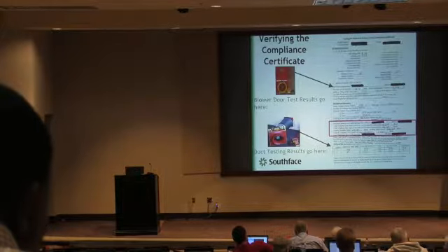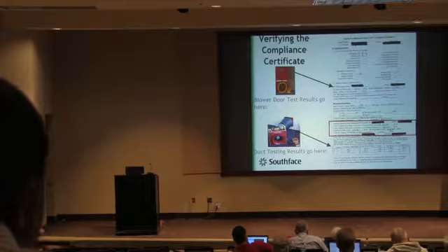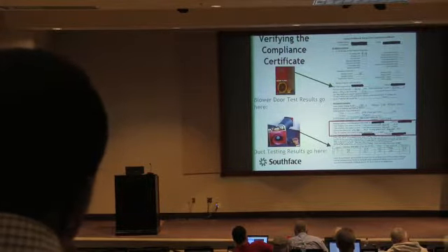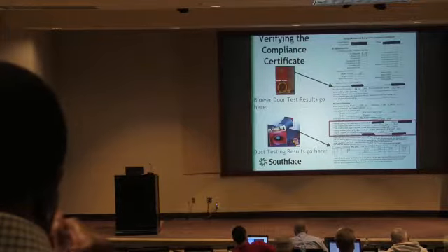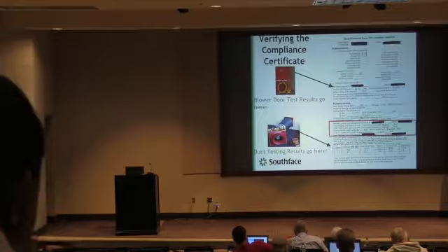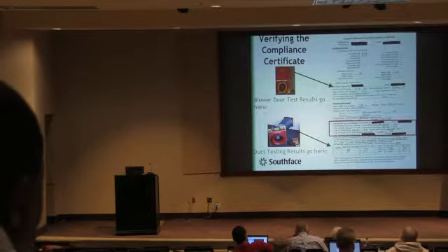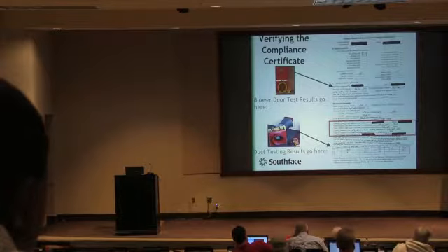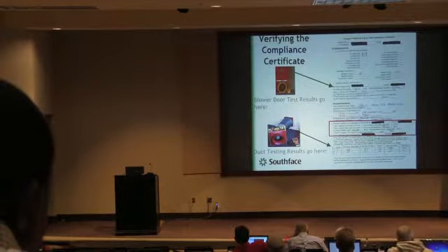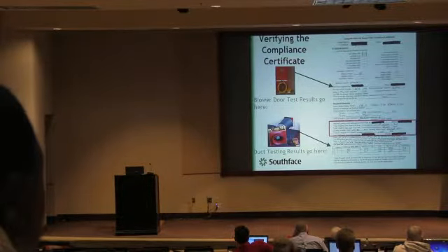You're incentivized, right? If you're the HVAC contractor, more tonnage is better, because of two things. The system's always going to make cold air fast. That feels good, right? Feels like callback prevention. And your price is based on tons installed. So a 5-ton system is better than a 3-ton system, even if the house needs a 3-ton system, because it always makes cold air fast, and you sold more equipment up front, and that's what your price is based on. So there is an incentive, if you're in that industry, to oversize.